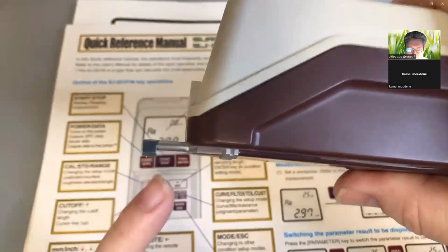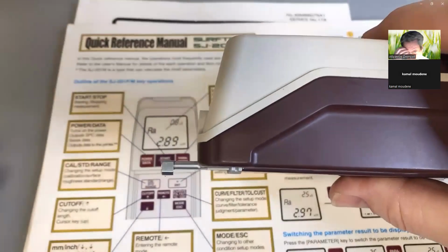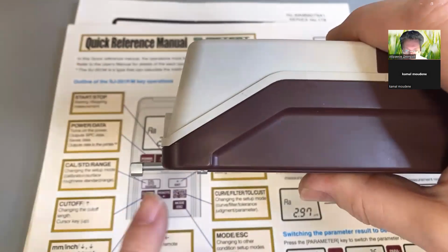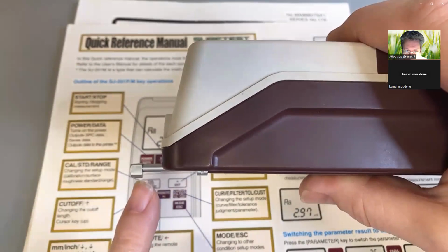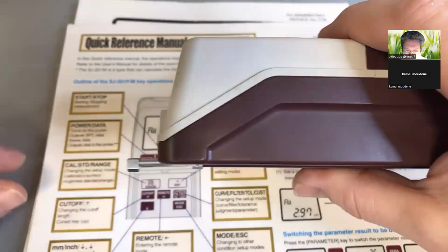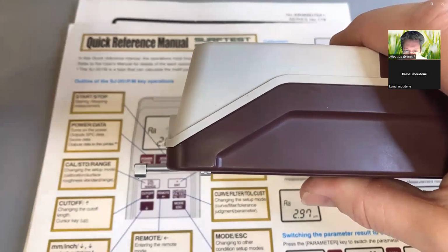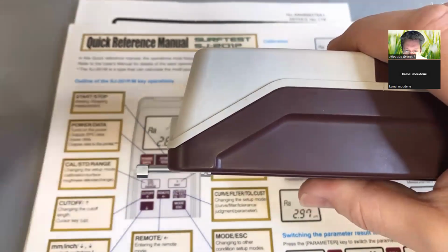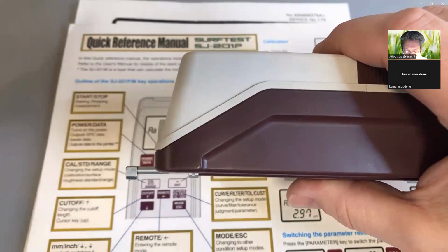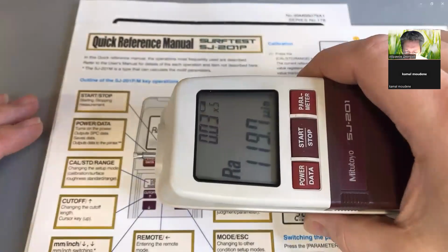If you take a look, you see that there's a tiny little needle sticking out the end there. That tiny little needle is actually what feeds back information into the system. But this is called a skidded type probe because it actually rides on the bump that's here. This can only check flat surfaces. It can't really check tapered surfaces or round surfaces. Now, if you have just the individual stylus sticking out, a non-skidded type, you can check round surfaces, tapers, and a few other things. But with this style, you're limited to only checking flat workpieces.